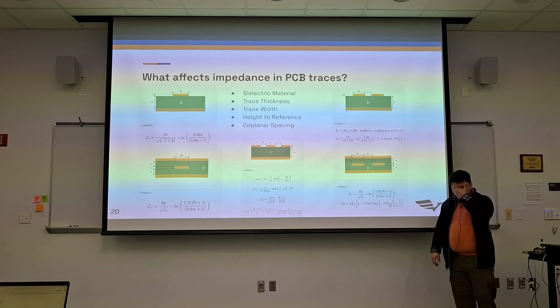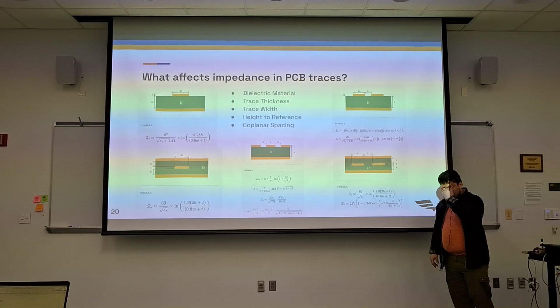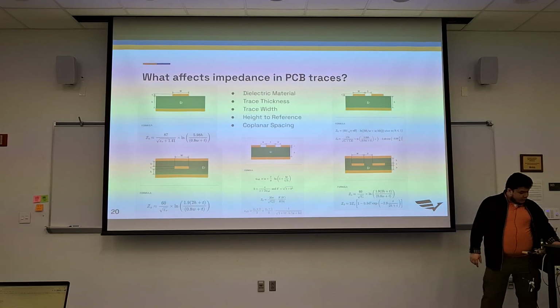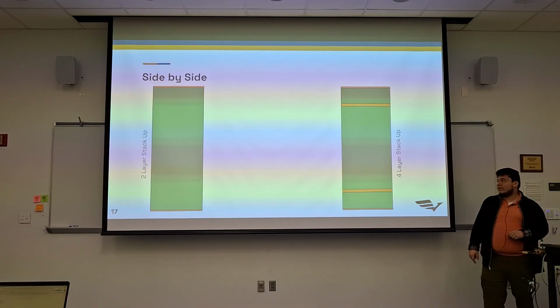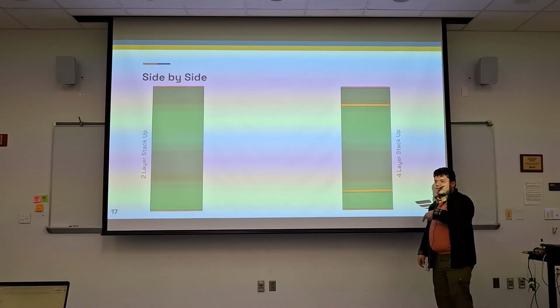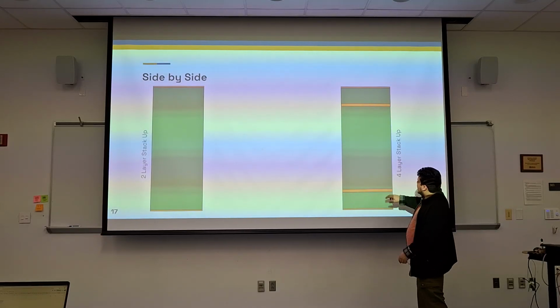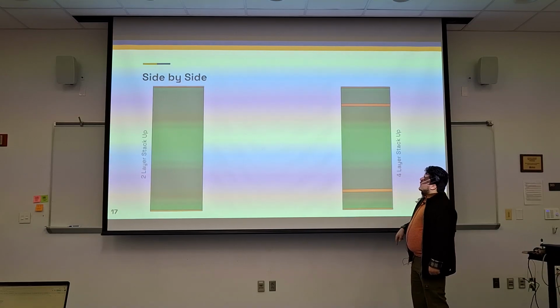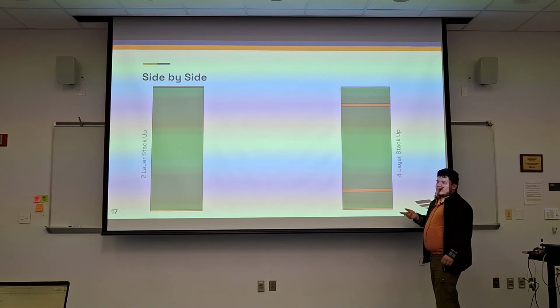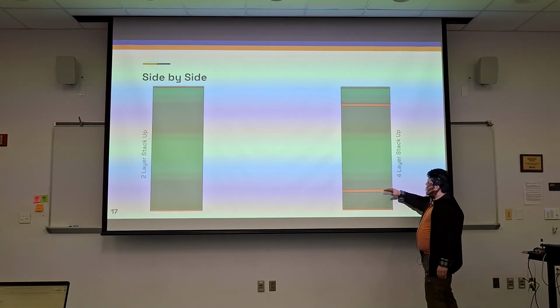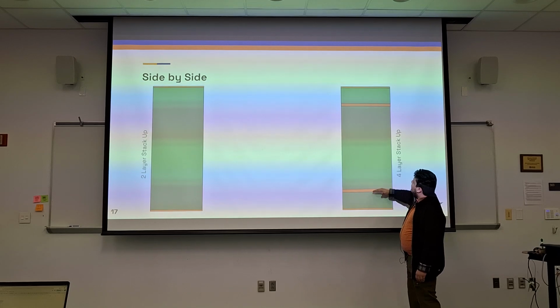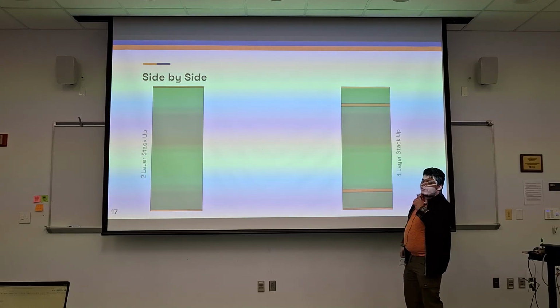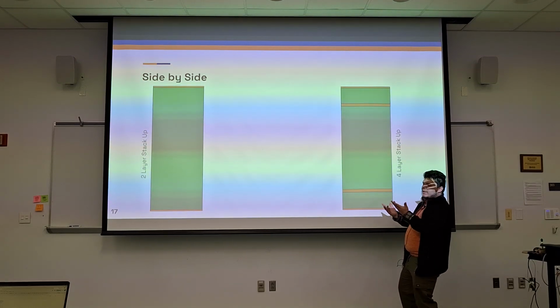Sometimes with 4-layer boards though, and here's the caveat, if you remember, 4-layer boards are not symmetrical. Striplines are symmetrical, so that assumes that these distances are the same. There's a calculator for it as well, for an asymmetrical one where you can choose these different heights. So you'd probably use that. It's similar, but it's asymmetrical.